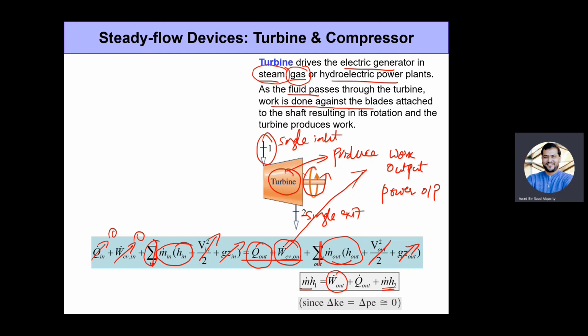The mass times the enthalpy that comes in, which is the energy that comes in, is used to produce a power output, which is W dot here, and the part that does not get converted to work goes out as m dot h2, which is of course a much lower enthalpy than the enthalpy of the inlet. So the work output is equal to the difference between the inlet and the exit enthalpies, right?